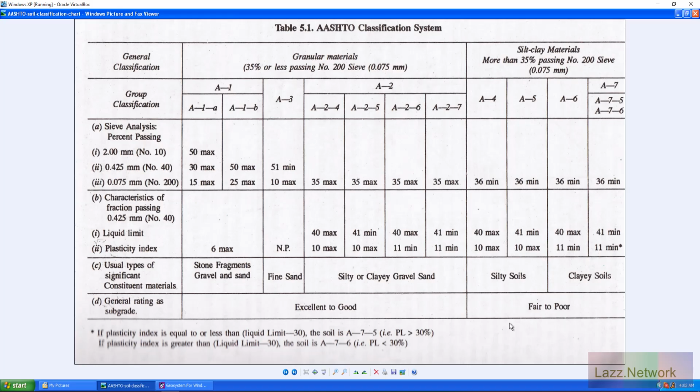And it really depends on what the intended use is going to be. If you have something that needs to handle a lot of drainage, you want something that can allow water to permeate or get through. If you have something with high fines, the water won't be able to get through as rapidly as something with lesser fines. So that's the other reason why the AASHTO classification system has this hallmark down here at the bottom to indicate that.